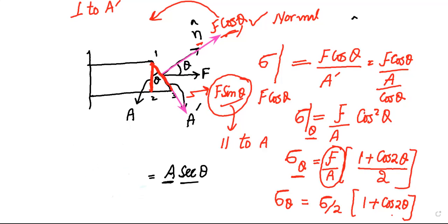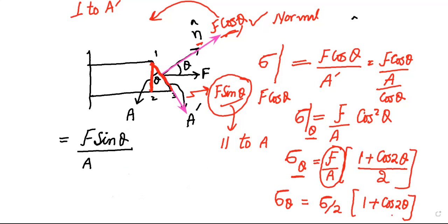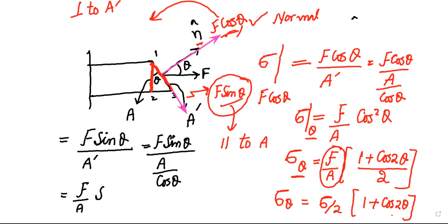The stress because of this F sine theta will be equal to force, that is F sine theta, divided by the area, that is A prime, which is A by cos theta. That can further be written as F by A sine theta cos theta.